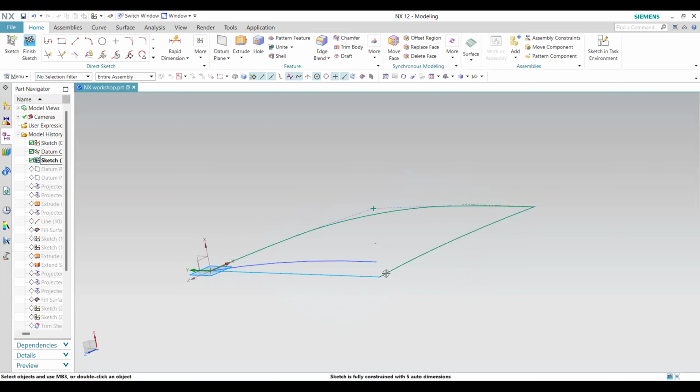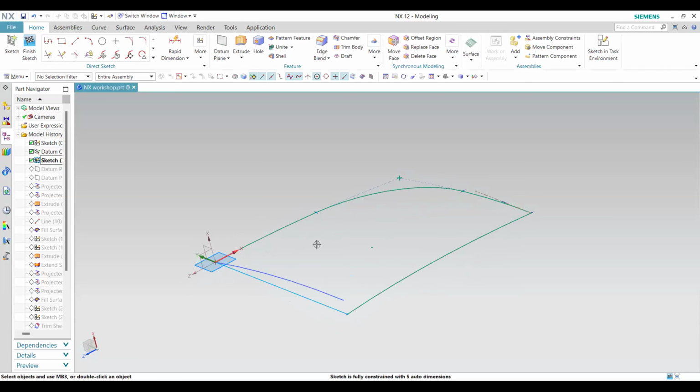In order to create a part out of it, in design, just for easier curvature, we create another line like this, similar to this one, at a distance, so that you get a neat profile all along your base design.